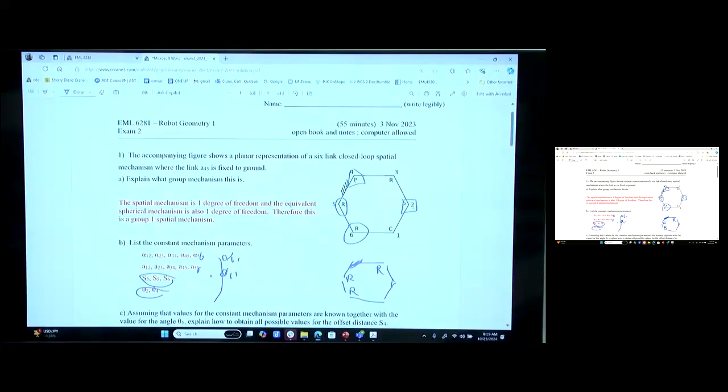I've got a prismatic, so I know that joint. And the cylindric gets mapped as a revolute. So for the equivalent spherical, the mobility equation for the closed loop mechanism reduces to the sum of the freedoms of the movable joints minus 3. Because I know those joint angles on 2 of them, there were only 4 movable joints, so 4 minus 3. Yep. And again, if I gave you one where the 3D had mobility 1,